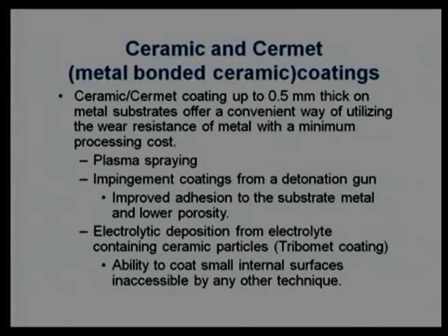maybe in air environment curing or a good regulated temperature environment. The only problem with plasma spray is dimensionality. There is a possibility of change in dimension. So, after doing this kind of coating, we need to do a super finishing operation on those components. And these coatings are now well known as wear resistance compared to friction reduction, compared to the lubrication.